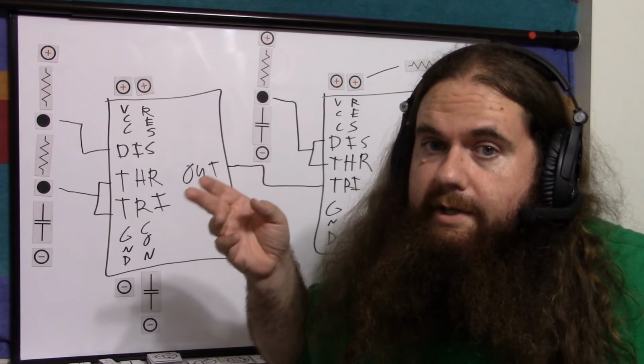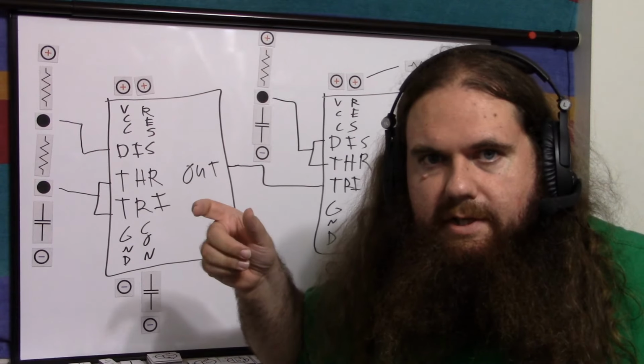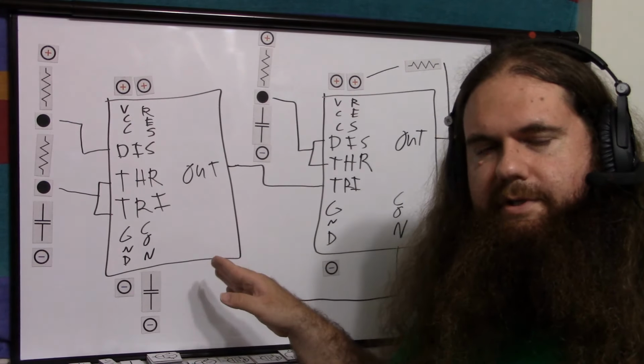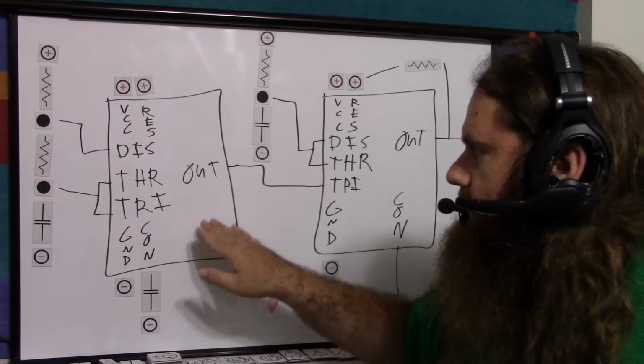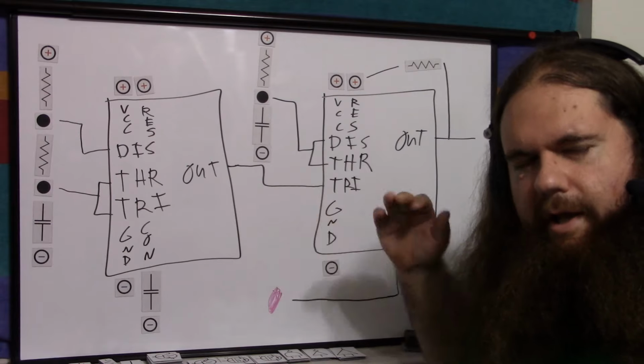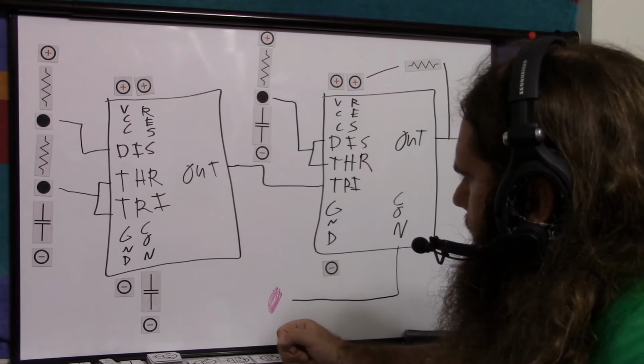Of course, it only outputs 500 Hertz. It's always the same frequency, so maybe that's not good enough for you. So if you want a different frequency of PWM, you're going to have to do it yourself. But that's it. This one generates pulses, and this one uses the pulses as a repeating timer. There's one thing I haven't mentioned, though.